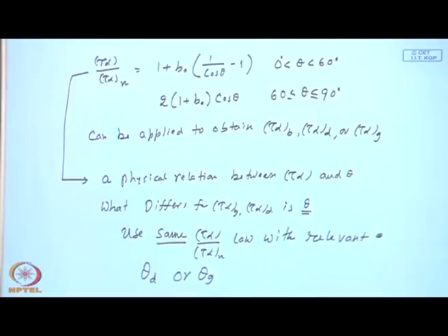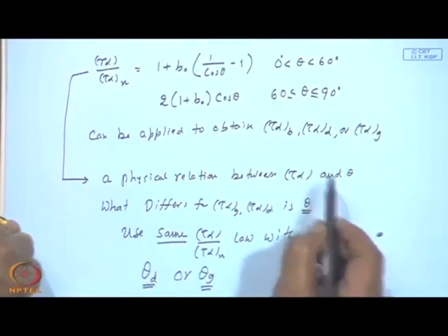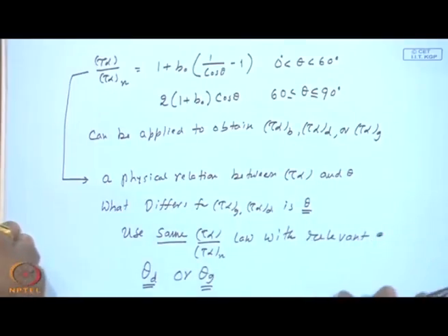If the effective angle of incidence for the sky diffuse radiation is theta d and the effective angle of incidence for the ground reflected radiation is theta g, then you will have the same law being applied using theta equal to theta g or theta d. For the direct radiation, we shall use theta b as has already been stated. So, next time we shall find out what are the values for theta g and theta d, and then how to define the weighted average or how to calculate tau alpha bar applicable for a day or a monthly average day. Thank you.